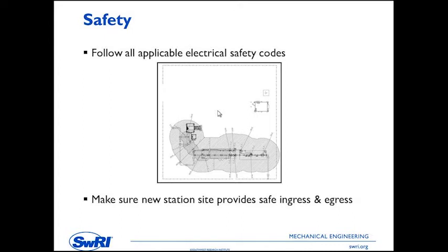One thing I wanted to point out about the site, the layout of the site is an important thing. You want the technician to be able to drive into the site. Typically, you want to be able to drive around all of the equipment. So these sites are normally finished with cover stone and such that they can accommodate heavy loads in the yard and get to equipment.